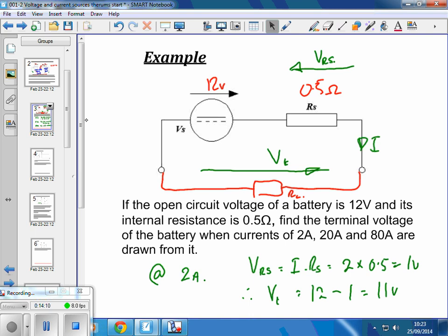The only thing they can vary actually is what's called the excitation of the generator. So they use the generator set down at Sizewell is not a permanent magnet generator. It uses a DC current in the rotor so that you've got a variable magnet, because they can't change the speed, because then the frequency would change.